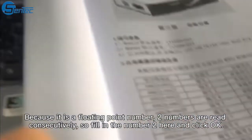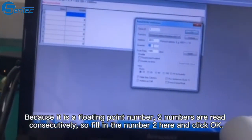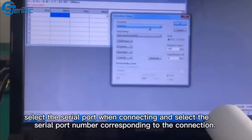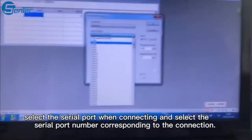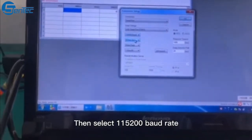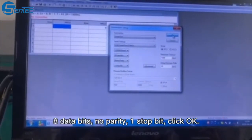Because it is a floating point number, two registers are read consecutively, so fill in the number here and click OK. Then click Connect. Select the serial port when connecting, and select the port number corresponding to the connection. Here we are connected to port 3, so select 3, then select 115200 baud rate, 8 data bits, no parity, 1 stop bit, click OK.